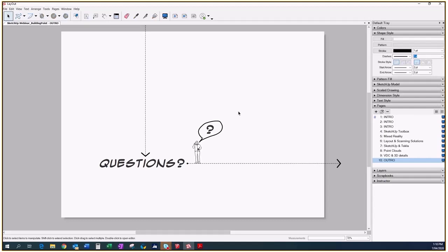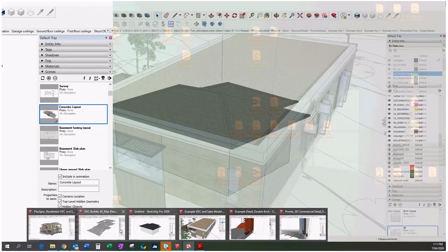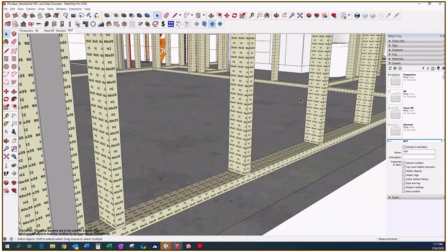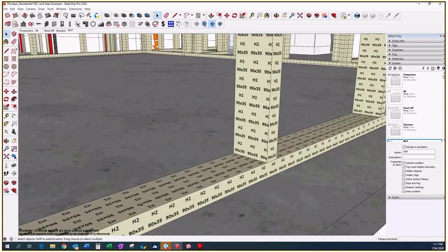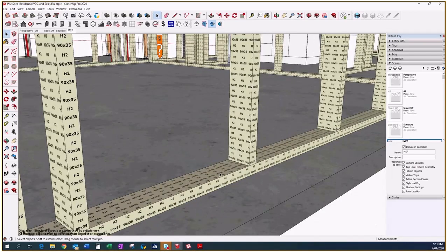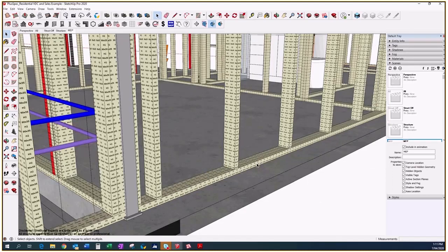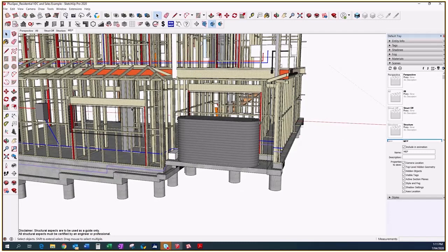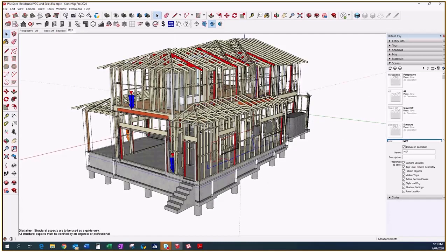If you're going to get a direct return on investment from having a full virtual design and construction model, spend the time. But I wouldn't put every screw in. Like you saw on the projects I showed you, it pretty much keeps it at the bare minimum, even though there's a hell of a lot in there. The bottom plates aren't showing how they're getting screwed down into the concrete, right? You're going to have to make that call. But I do think that level of detail is important.